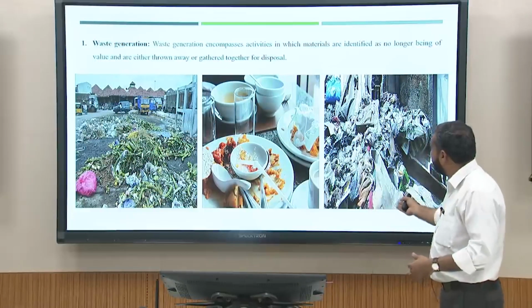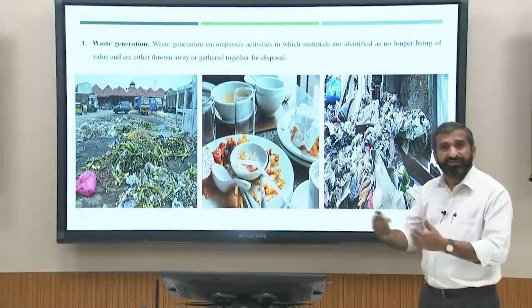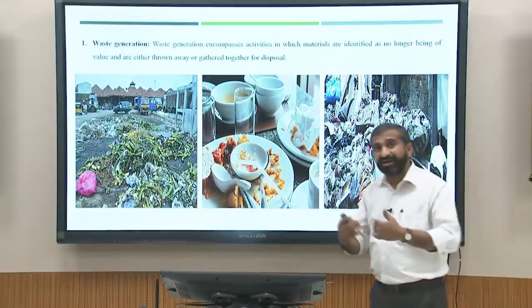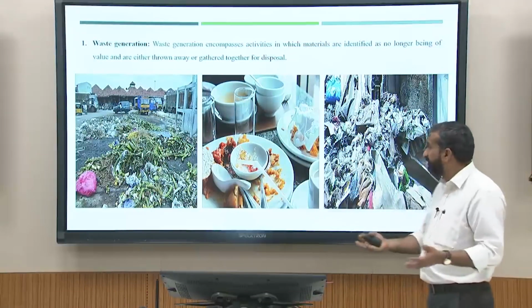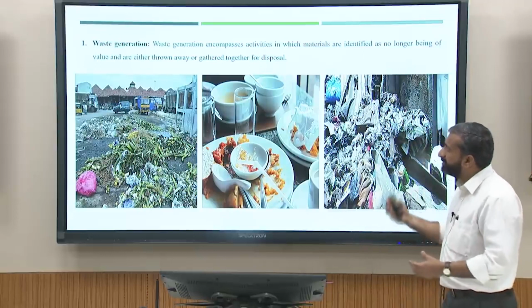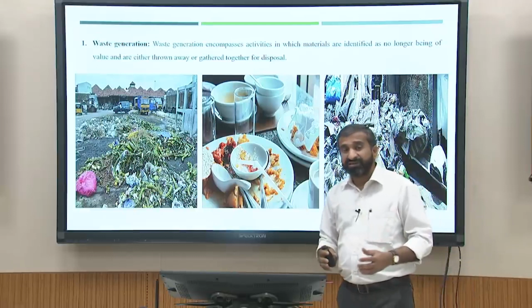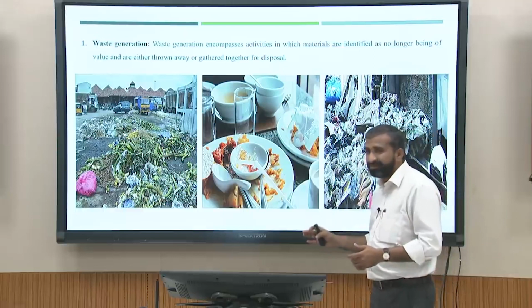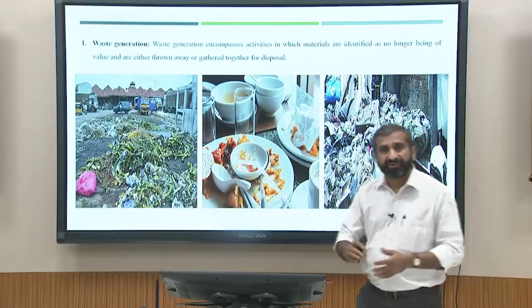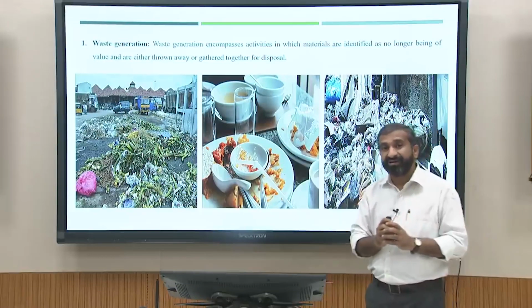The other photograph is showing a lot of plastic and dry matter, which is easily recyclable matter. Also, this kind of waste can produce a lot of energy, or we can have proper incineration or a waste to energy plant. So, in this functional element we will talk about not only the different sources and different compositions, but also the different characteristics of the waste, because once the waste goes for the transformation or treatment process, you need to know the physical, chemical and biological characteristics.